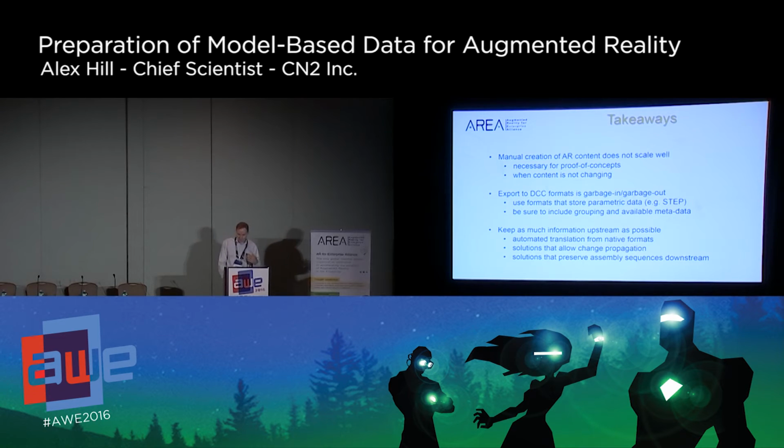The final takeaway has to do with keeping as much of the upstream data in as possible. The later you do the translation, the better. This is why you would prefer to use a native format. And like I said, there are a number of companies who will say that they import these formats directly, but most likely they're using some form of translation on their side. That gives them some control over level of detail and decimation.